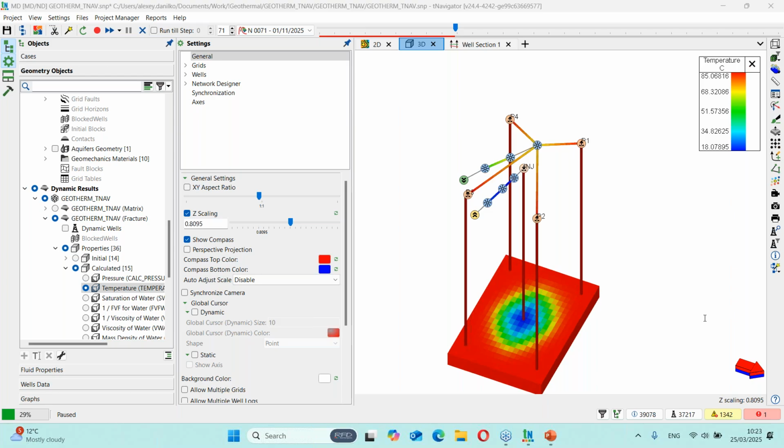It says, are you running a finite difference calculation in the reservoir grid and nodal analysis for the wells and pipelines? Yeah, so this is a fully coupled project. In this case, we don't transfer the results as an IPR, like a nodal analysis for the pipeline. The network model and pipelines, as you mentioned, are fully involved in the calculation. We have the same calculation time steps for the subsurface, the pipelines and the wells, so we don't need to make an additional nodal analysis on the pipeline.